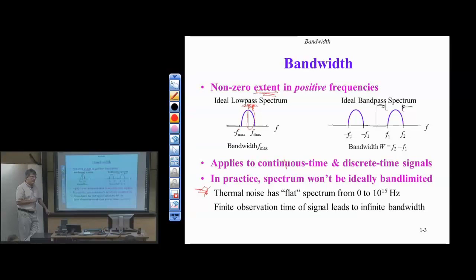Why would having that higher sampling rate make you care less about thermal noise? Well, no, we do care about thermal noise because the frequencies we care about in a discrete time system go up to tens of gigahertz. Right now, 64 gigahertz is kind of our upper limit.